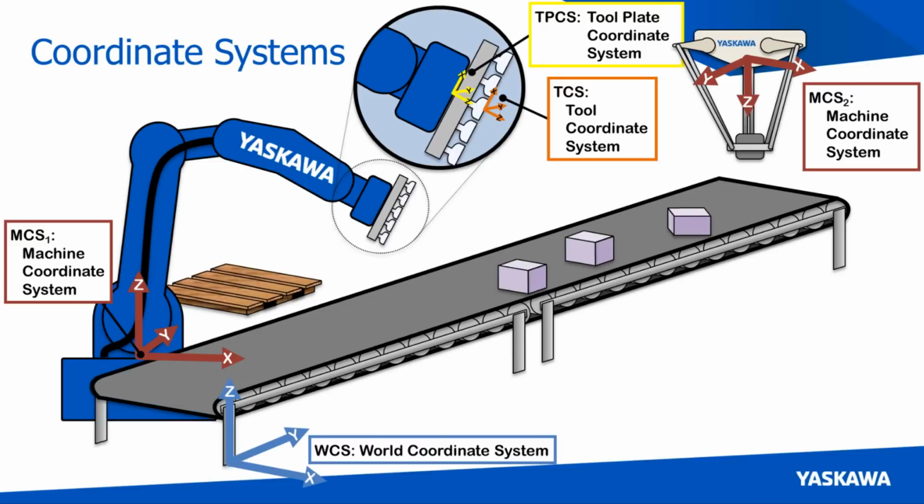The end result is something that we're very much going to be talking about a lot, and that is the tool center point, or the TCP position. That is going to be where we are moving. When we say move to a certain MCS position, it's the tool center point that's going to be moving to that MCS position. When we say move to a particular part coordinate system, it's going to be that tool center point, or TCP, that's going to be moving to that position. So that's kind of the output of all of the kinematics and the tools that are on there.